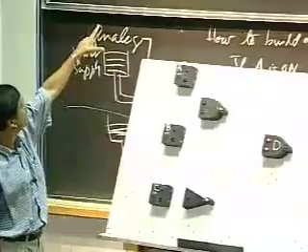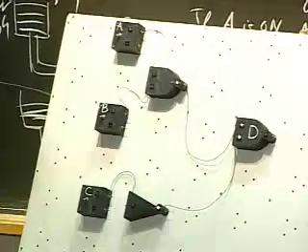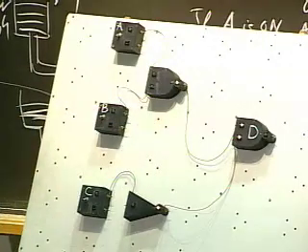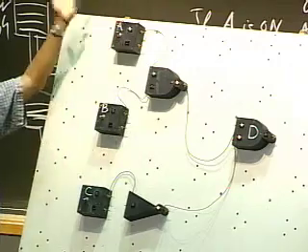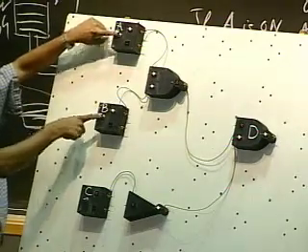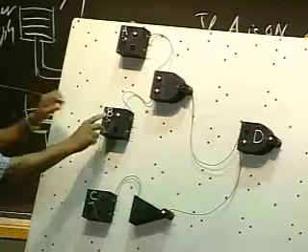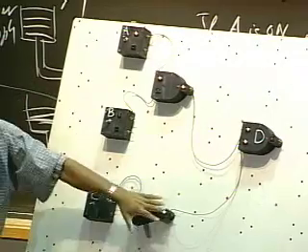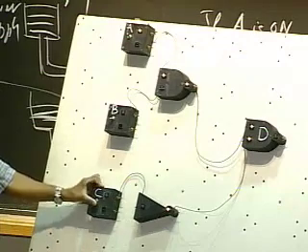So here's a little circuit that I showed you here. A, B, the NAND gate at the output, and the inverter. This output is going to be 1 whenever either A or B is off. So the output is a 1 in this case when both A and B are off. I turn A to 1, output is still a 1. So the moment I turn both of these inputs to a 1, the output goes to 0. That's behavior of a NAND gate. If I switch any one of the inputs to a 0, the output should go to a 1. Similarly, for the inverter here, when the input's a 0, the output's a 1. And when I switch it, so should the output.